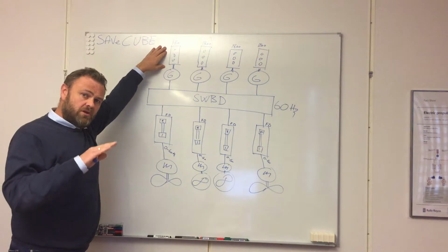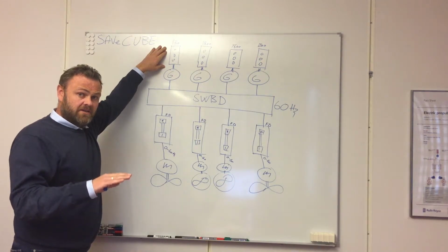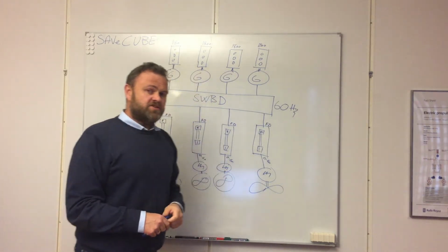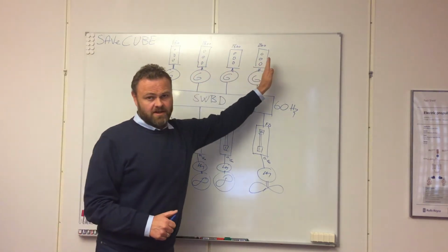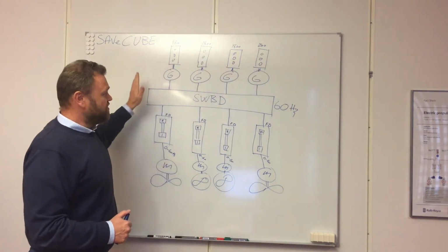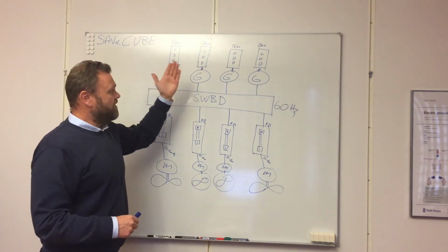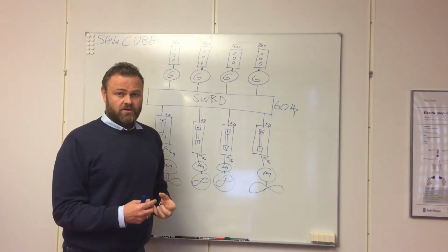If we are able to lower the speed of the engine in low load conditions, then we can save fuel. You know, the reason why we have many engines in a diesel electric system is that you are able to stop and start engines based on load.